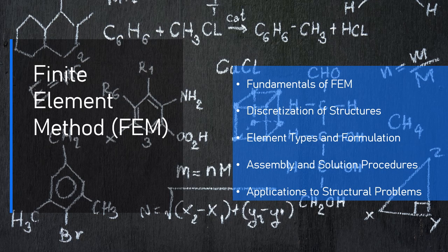4.6. Nonlinear structural analysis. In real-world applications, many structural components exhibit nonlinear behavior under loading conditions, e.g., large deformations, material yielding, plasticity. FEM is capable of modeling both geometrically nonlinear and materially nonlinear behaviors. 1. Geometrically nonlinear analysis. This type of analysis considers large deformations, where the displacement of the structure is large enough that the assumption of small deformations no longer holds.